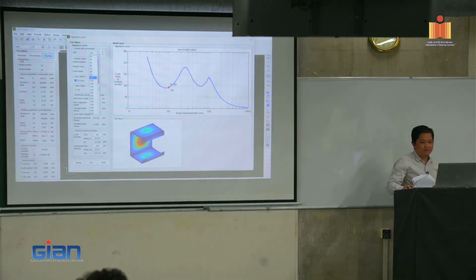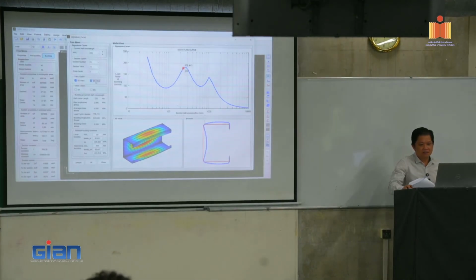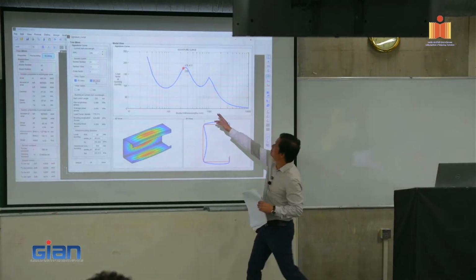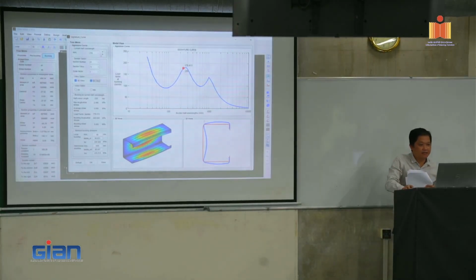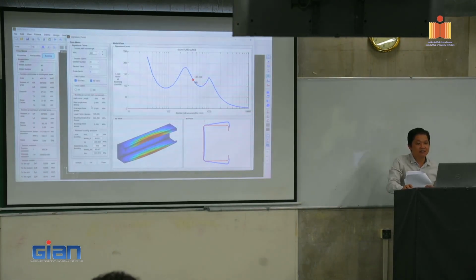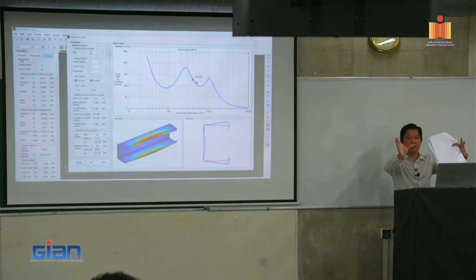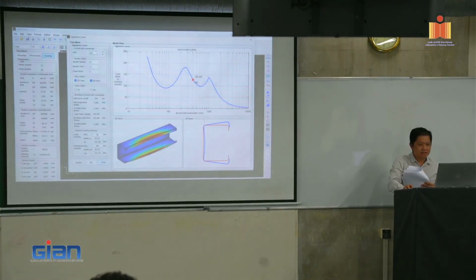And then if we go up to a little bit longer half-wavelength, you see that it starts to shift from local buckling to distortional buckling. And if we keep going to 350, no, the maximum is 500, 400 now, it's really distortional buckling. Okay, so it's open now. So it can be open or in, doesn't matter, right? It's changing the half-wavelength. You can have that. And then it keeps going to 500 and 2000, okay?